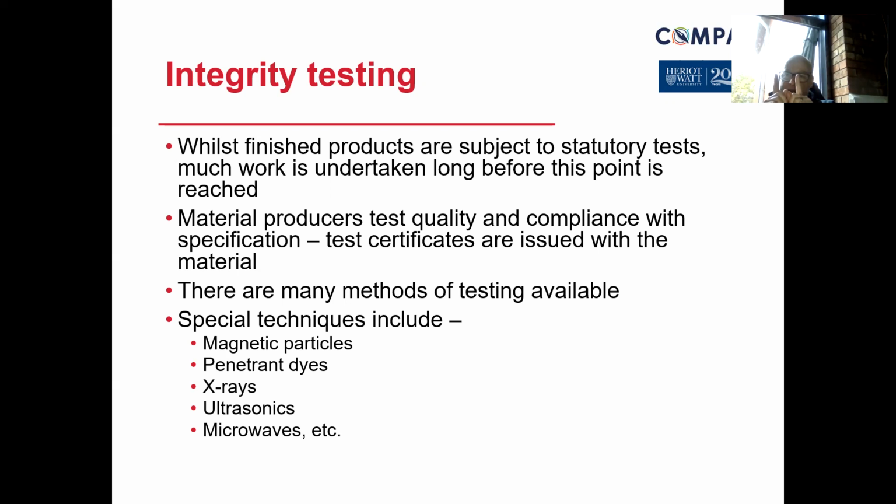So if the crack's only that long, it's okay. But as soon as it gets to that distance, that means it's unsafe. And therefore, we've got to take that out or replace it. There are other non-destructive testing methods available, used in situ and regularly by thorough examiners under LOLER to do those tests.